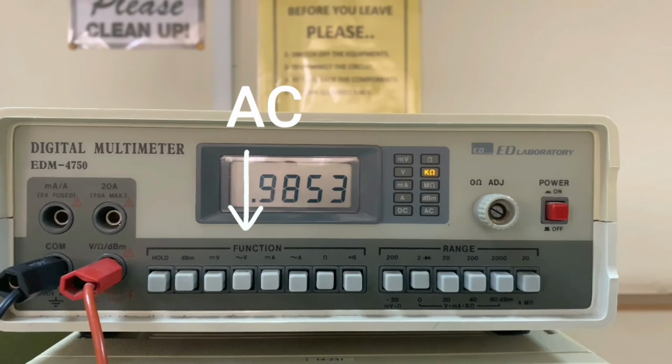To choose the proper range, if you get, for example, 1, that means you need to choose a bigger range. Go to the next one, you will find that it's 0.98, and here you will find the unit, kilo ohm, and our resistor is actually 1 kilo ohm.